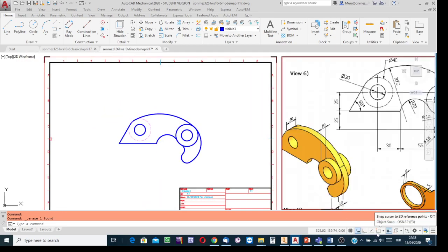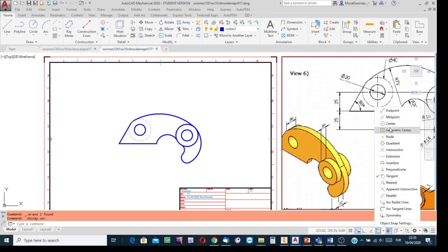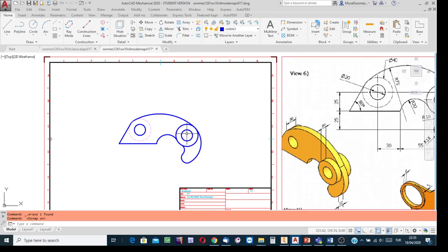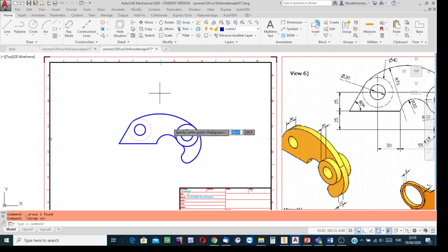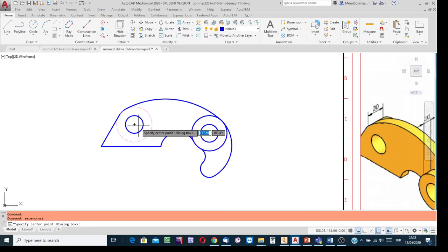Well, here to be able to indicate the center points, I'm going to use right now the classical snap facility. Click on this and then check whether center points are enabled. If not, make a click here and enable the software for your indication. Okay, start the symmetry axis creation process, center line cross, and then, thanks to snapping, you can indicate the center and then indicate the midpoint of the outer circle.